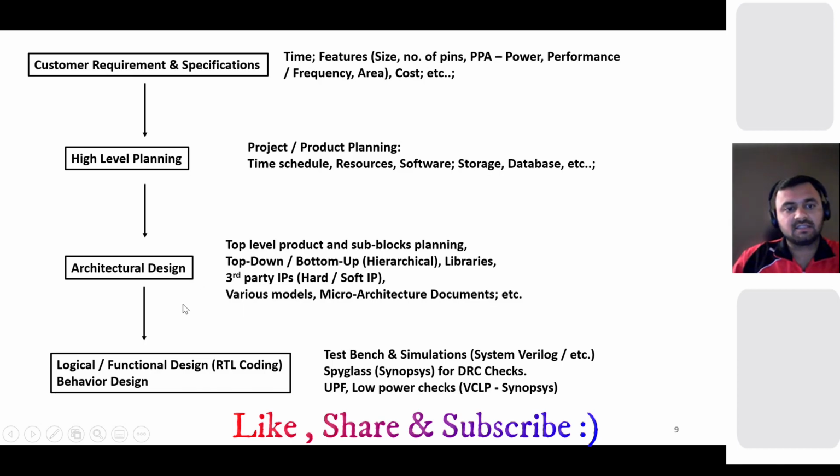And once that is done, it goes to the logical and functional design, where you do the Verilog RTL coding, your behavioral coding, and you write the test benches and do the simulation. Currently, they are using SystemVerilog extensively for this purpose. And apart from that, you check the DRCs and many RTL and other rules here. So you use Spyglass, it's a Synopsys tool, for clock domain crossing and reset domain crossing, which I'll be discussing in detail. But here basically you check those DRC, design rule checking.